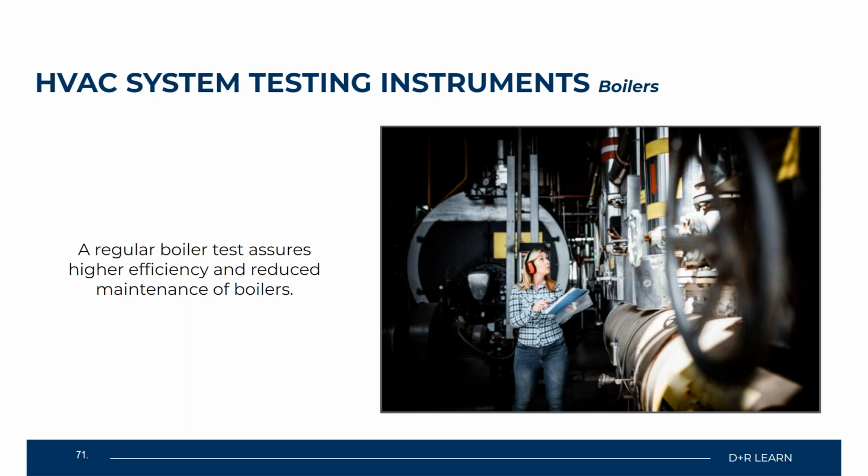And then you're also going to be sending supply and return temperatures of your hot water to your BAS, or building automation system. And we all know that's for logging. We want to make sure we have all those diagnostics inside of our log, so when we return to it at a later date, we can have those readings for evaluation.